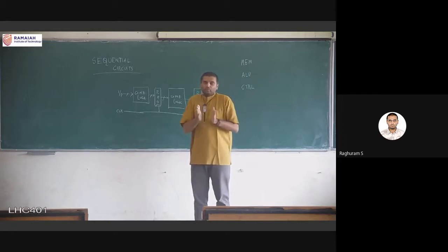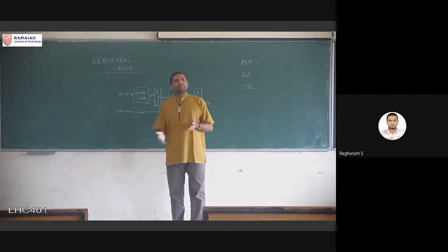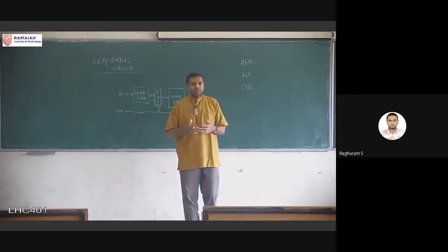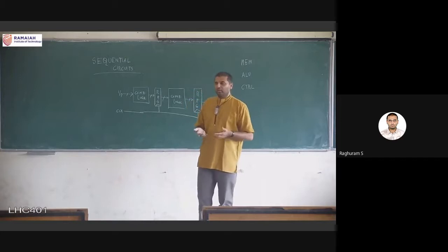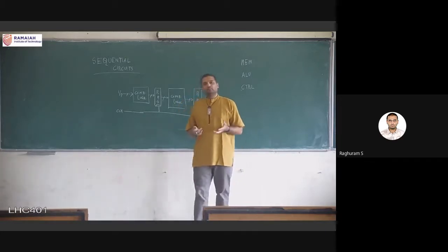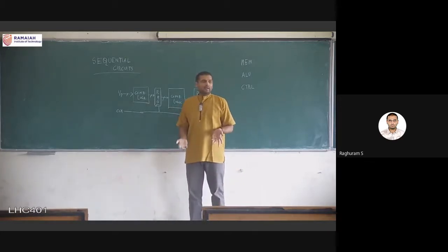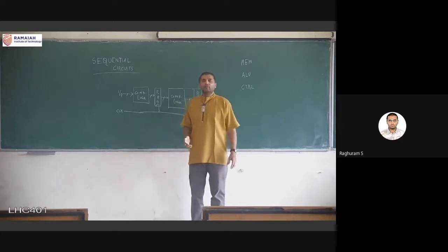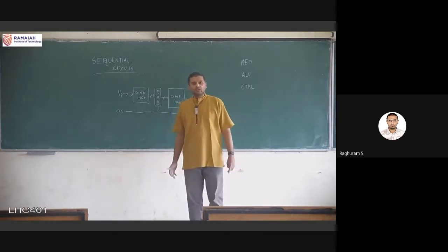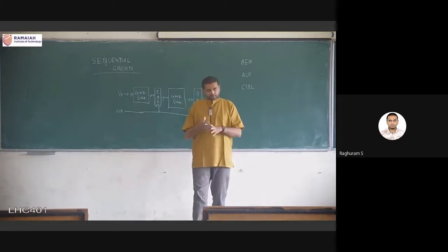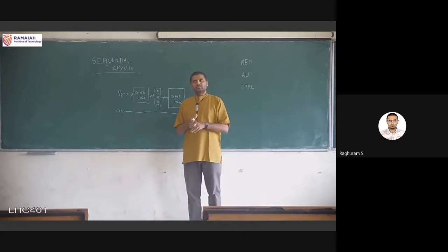And when all the outputs are ready, we have to design the clock signal such that all the outputs are ready. Clock signal is not an automatic signal, right? Clock signal depends on the functionality that we have. Based on the functionality, the designer might say, okay, for this type of image processing or video processing functionality, you can have, say, a 500 megahertz clock signal. 500 megahertz translates approximately to a 2 nanosecond clock, I think.